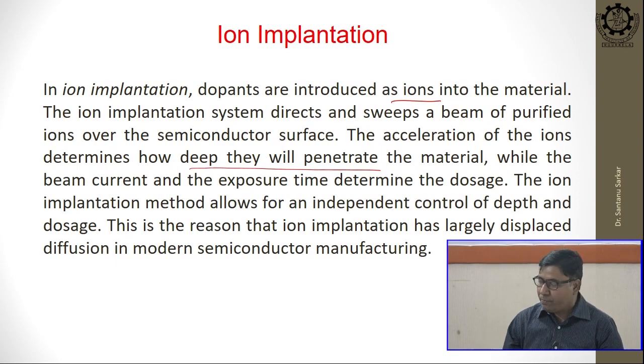Clear? In the previous case it was just a gas, and in ion implantation it will be used as an ion, and a certain voltage and electricity will be used to set the acceleration of that ionic beam, which will define how deep you want to go. So, according to your depth, the fabrication designer will decide all those values.